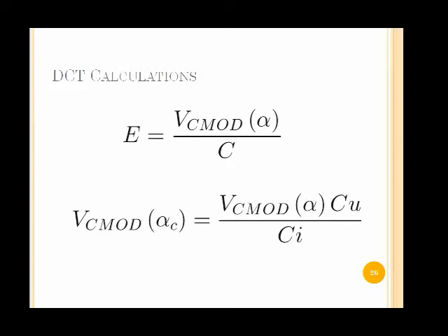The reason this looks a little neater than the other one is, A, we don't have to worry about self-weight of the specimen. Because we're pulling it in tension, any weight of the specimen is already being read by the load cell. So there's no unaccounted for load on the specimen. With the single-edge notch beam, all the machine is doing is just pushing down. So the specimen itself is also providing, through its weight, a downward force that needs to be accounted for.